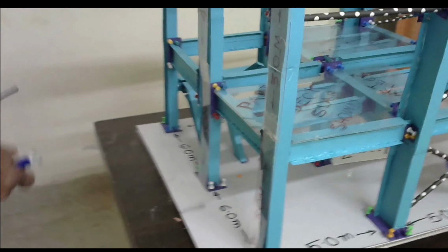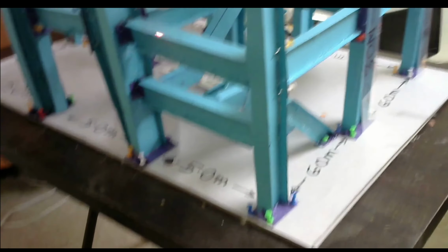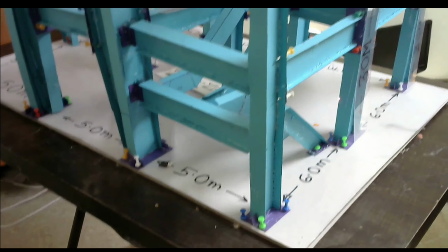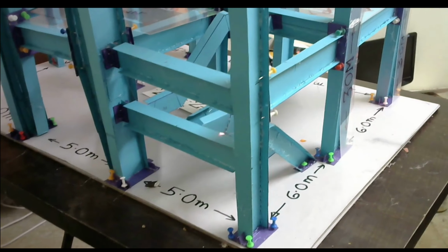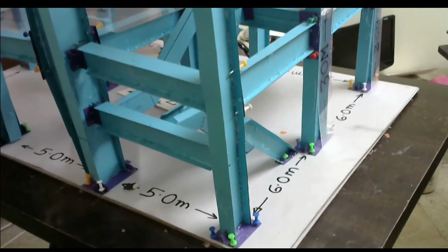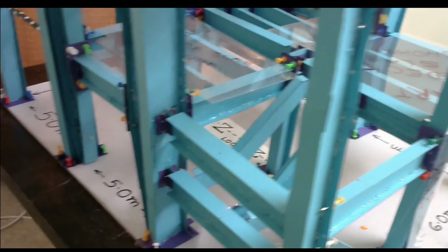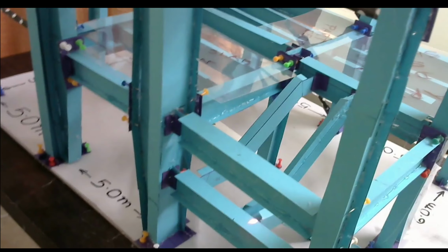Now there is a special case for these two beams. See, there is no deck slab for this. Obviously there will be some deck slab here, but this stringer will provide adequate restraint, so we can leave it to the LX LY parameter as per STAAD.